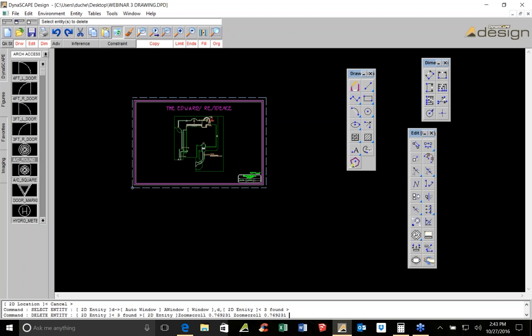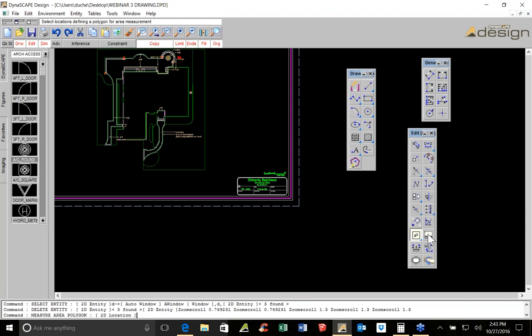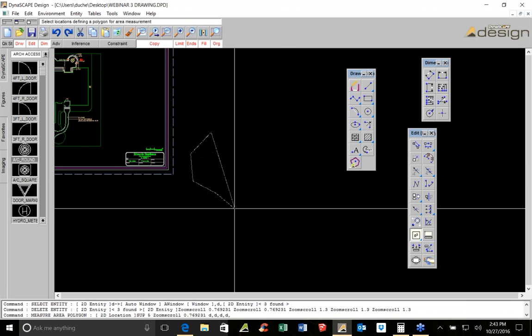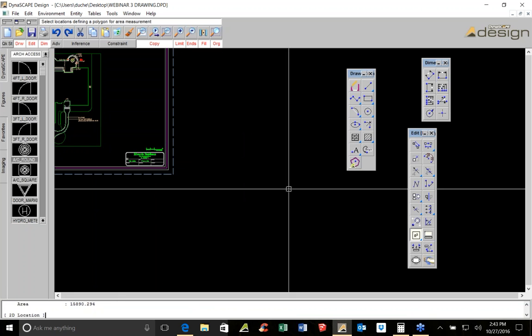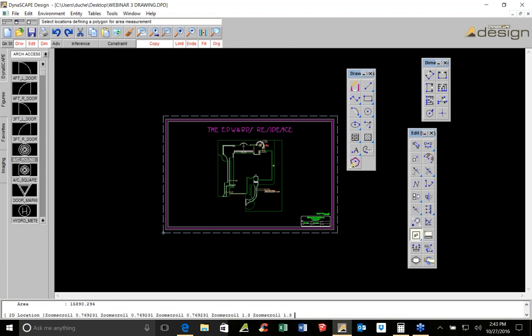Bring your drawing, bring your survey right in here as an image, rescale it, and then literally all you're doing to measure these things, you know, if this is a lawn area on a plan, you're really quickly getting these square footages and making notes. So not only are you able to estimate and dimension plans that you've drawn, you can really quickly do takeoff on JPEGs and PDFs. So that's really about all I have with all of this.